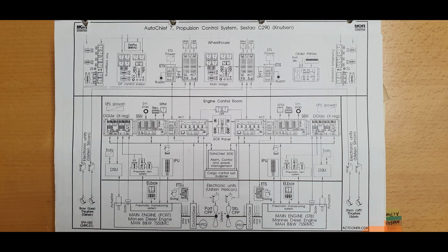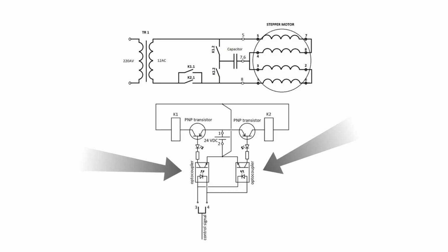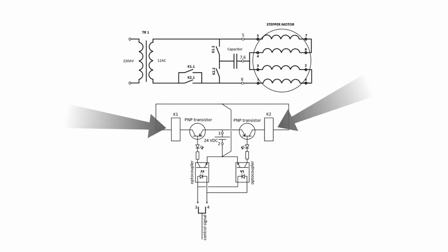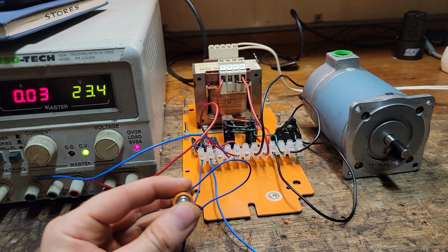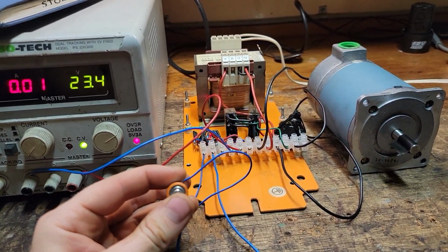The control circuit consists of optocouplers, to which a voltage signal of different polarities is applied depending on the direction of rotation we need, and this was seen in the example with batteries. And depending on the polarity of the voltage, the optocouplers control the transistors that supply power to the relays K1 and K2. The control circuit is powered by 24 volts. The result is the following electronic construction. Also, I needed some time to choose appropriate current limiting resistors to avoid overheating electronic components.